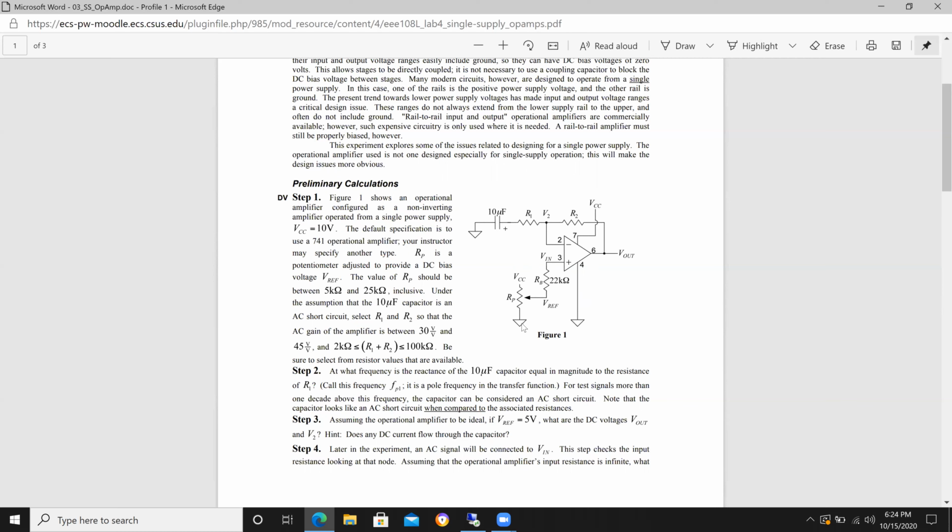If you're not familiar with it, this 3-terminal device right here is a potentiometer. So you've got your 2 terminals like a standard resistor, then you've got what's called a wiper in the middle. All right, so let's talk about the bias part of the circuit first. The whole point of RP and RB is to set a DC potential at VN right here, okay?